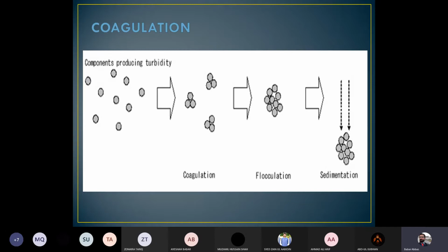turbidity, physical contamination from the water samples, and this is called physical treatment as well as physico-chemical treatment. Physico means that we are removing the physical suspended particles from the system, and chemical means that we are adding some chemicals to make these flocs and then remove them from the system. So it's a combination of both physical and chemical processes. That's why we call the water treatment at this level a physico-chemical process, and it results in the removal of the physical contamination in the water samples.